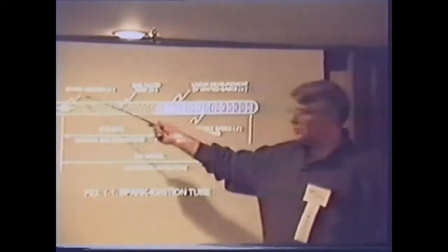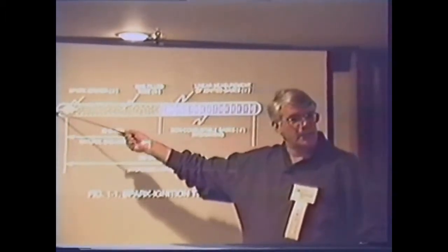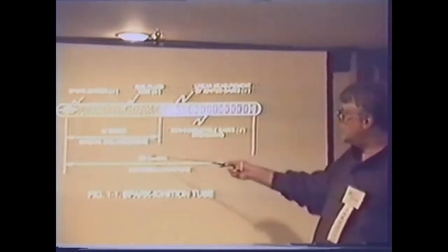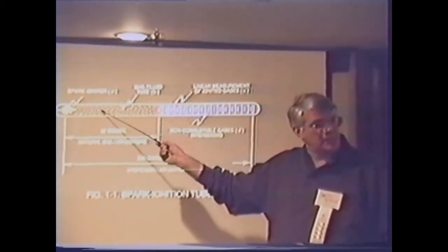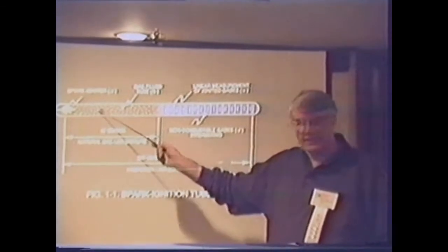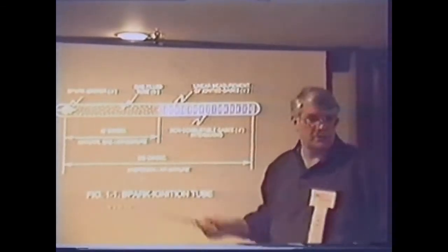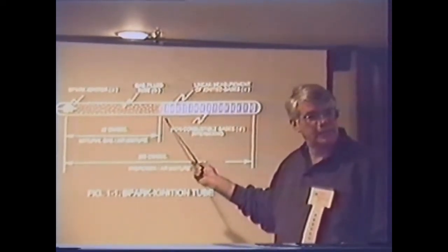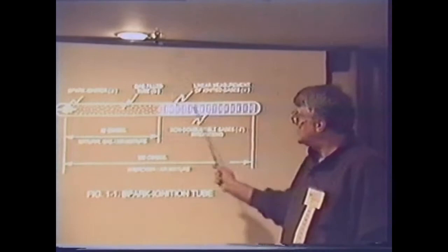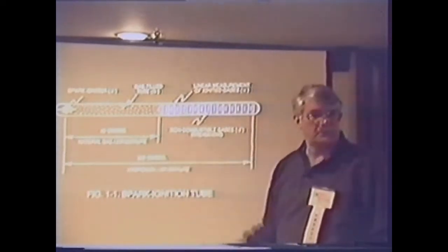All right, if I had a flash tube here, filled with hydrogen and oxygen and air, if I ignited at one end, you measure it in 1 second, it'll burn 325 centimeters. If I put natural gas in here and mix it with ambient air gases, it'll burn 42 centimeters in a second. So it became very obvious that if I would take the non-combustible gases and mix it with the hydrogen gas and the oxygen, I now can adjust the burn rate to co-equal that of the fossil fuels.